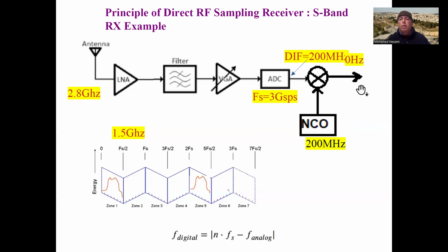So you can estimate the offset from your preambles and midambles, whatever, and then figure out how much you need to shift that baseband signal. So if there's an error, you can introduce a correction so that you're getting rid of that offset, so that you're sitting exactly at 0 hertz.